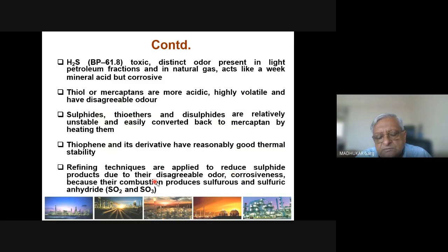It is not only important for us to reduce sulfur in the fuels that we use, but also sulfur in various streams which are treated using a catalyst, because some of the catalysts can be poisoned with sulfur. As you'll see when we discuss technologies like catalytic reforming, isomerization, or even steam methane reforming, we remove sulfur in the stream to less than 1 ppm.